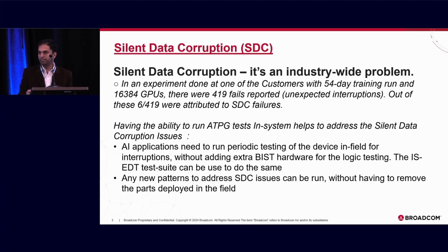The other thing is that with changing technology, if we have top-up patterns or some new patterns, new fault models, we don't need to take the device out of the system and ship it back to the lab and run the test there. We can run the test in system as well with the new patterns or new fault models.